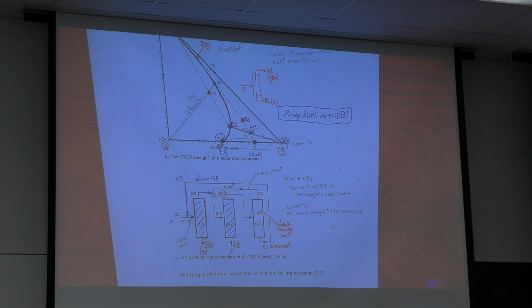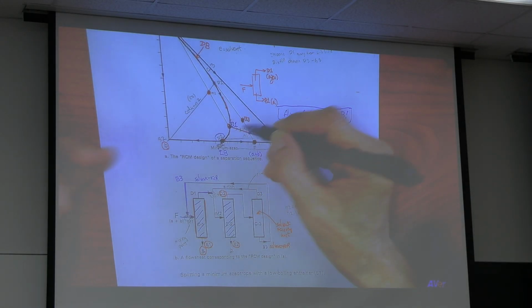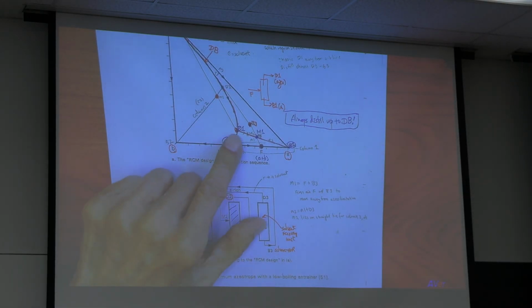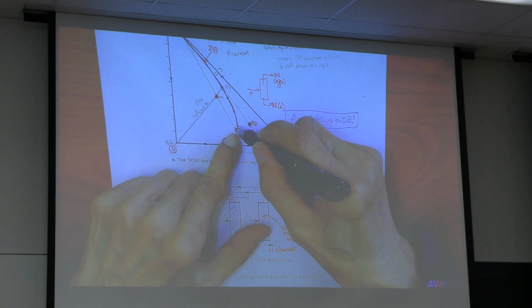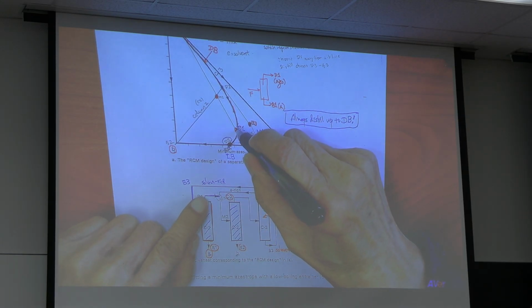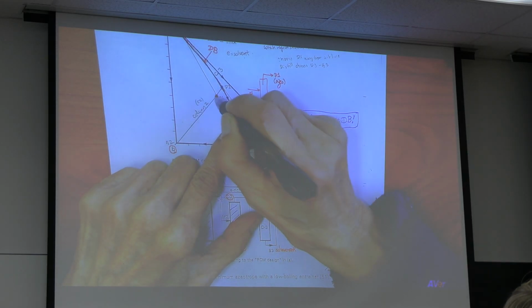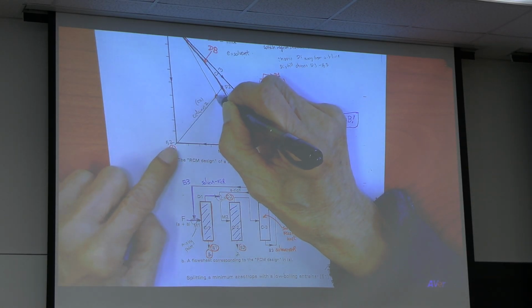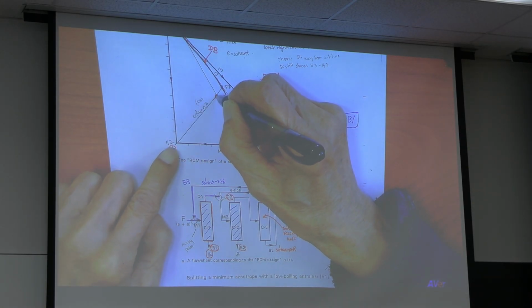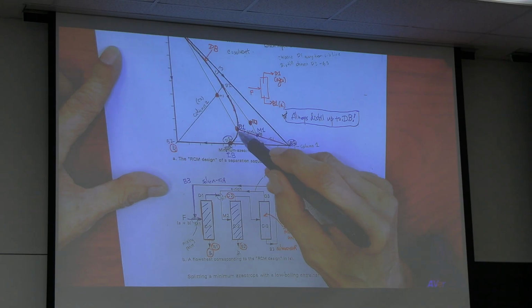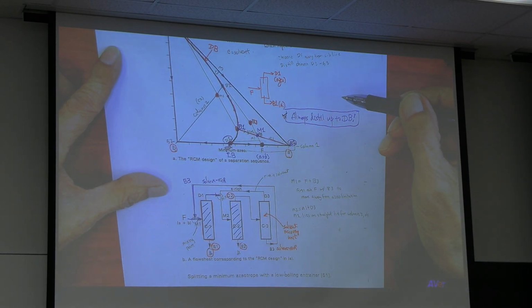Why do you put D1 there? If I put D1 here, it does nothing. I cannot cross the distillation boundary. You always distill up to the distillation boundary. I got D1, right? Then I can find a stream to mix this, creating a new feed. That is the feed for the lovely B product. So, trick: always distill up to the distillation boundary. D1, right?